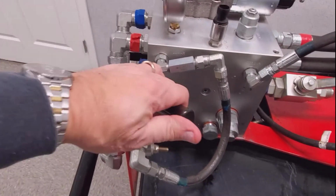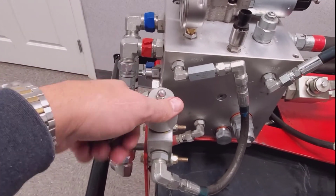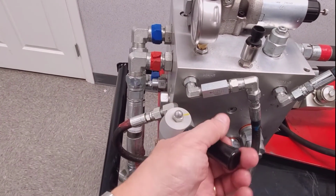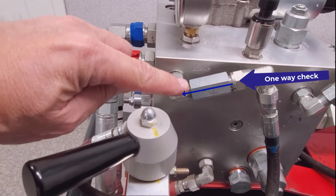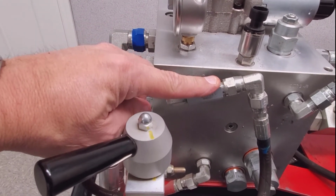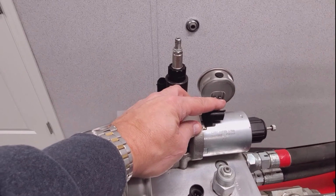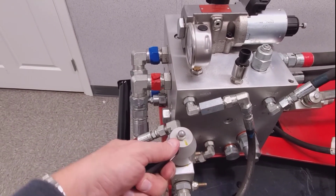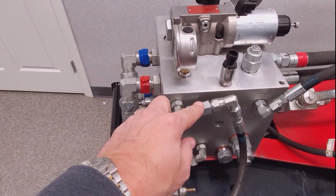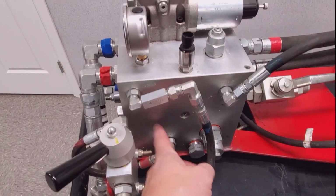We have this valve we can cycle to raise and lower the openers, or the frame, sorry, to adjust our depth, and put it back down. We have a one-way check to make sure that oil is always going the right direction so it can't run backwards. Before, I talked about how cutting the power here would verify direction of oil. Also, if my QDA works, the oil is running in the right direction because of the one-way check in here. And again, if it had AccuSet, it would be using the same two ports.